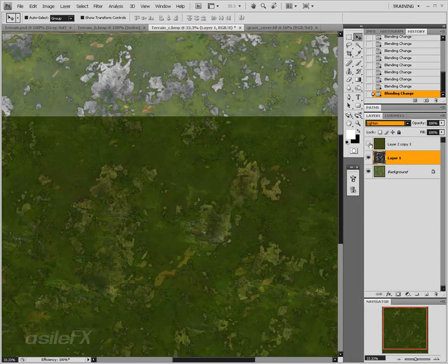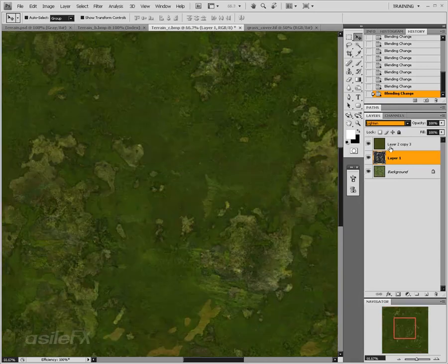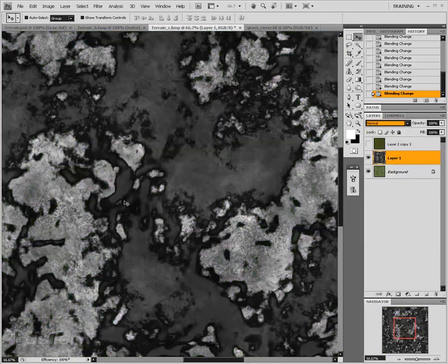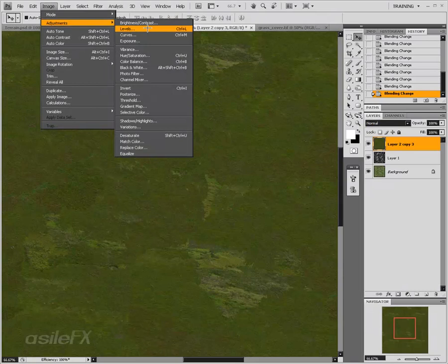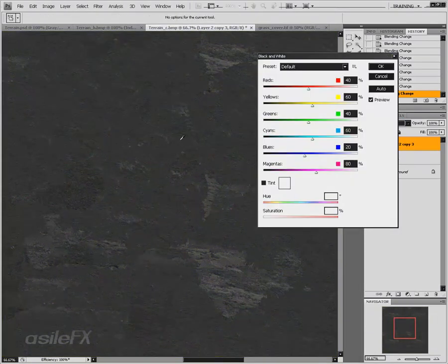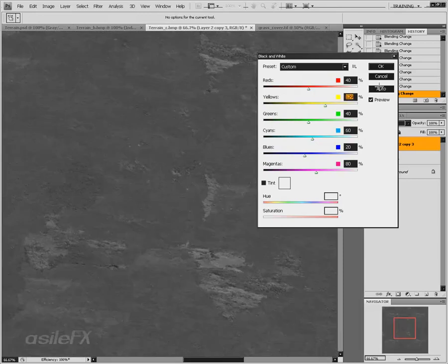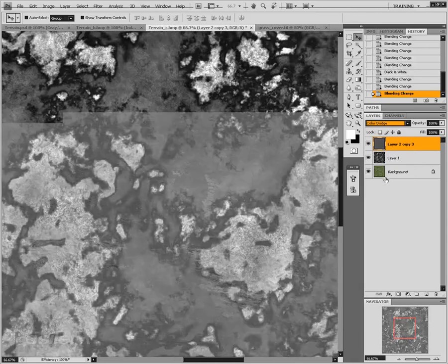and the bump map will also need to be modified, improving the quality since we resampled it, changed the scale. So we'll go ahead and save this out really quick and we can go over to view. And just a really quick way to modify that bump map. I'm going to set this to normal mode and then select that grass layer, go to image adjustments, do black and white, and now we can create a bump from this image map, or at least a layer we can overlay on top of it.